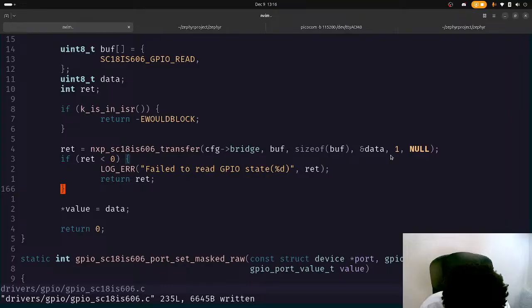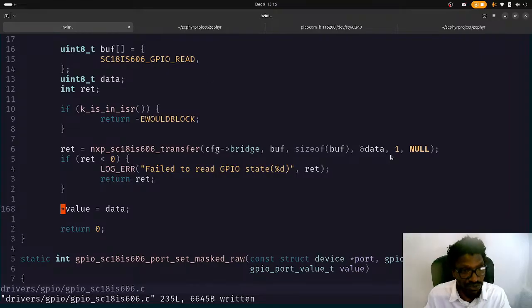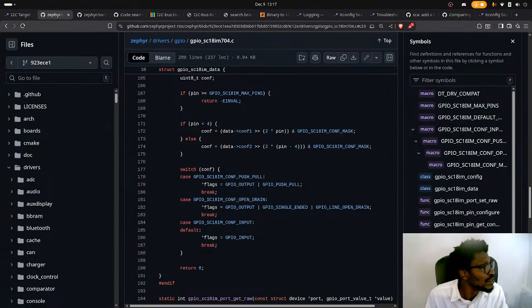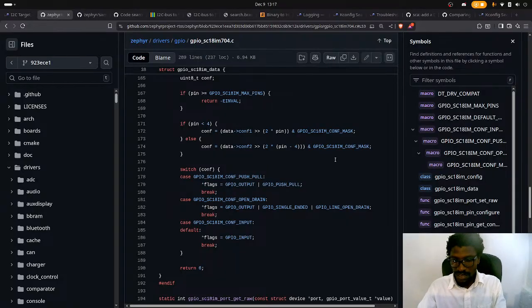So I can probe 0 and 1 and see what happens. And maybe they're just flipping so fast that I can't see. So cool. Sorry about that. What I'm going to do here is run PulseView quickly.